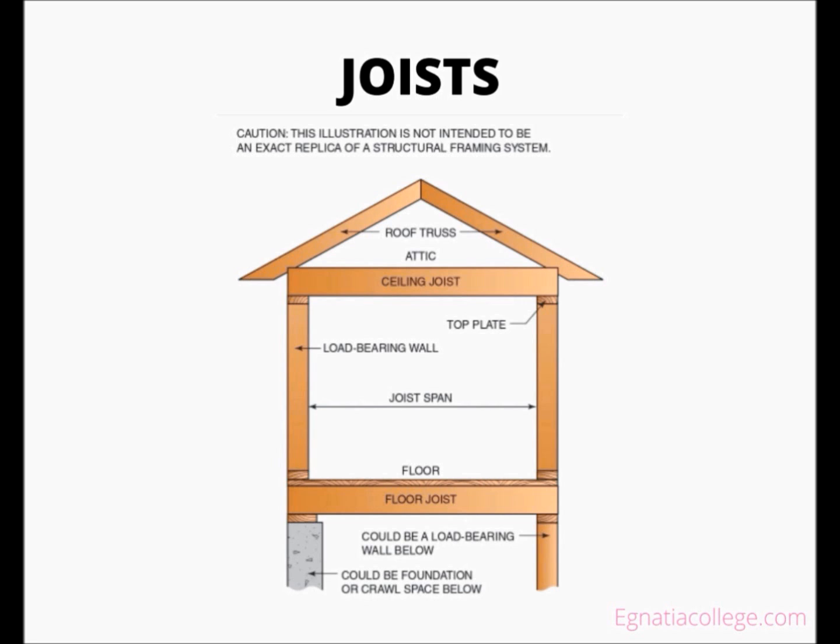Thorough code knowledge is required before drilling and notching joists. A joist can be difficult and expensive to replace, and an inspector can demand that a company provide a certification from a structural engineer for a joist that has been altered.